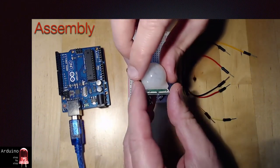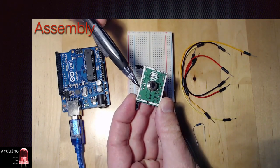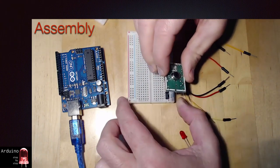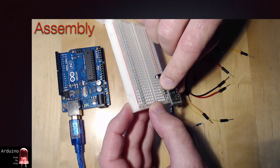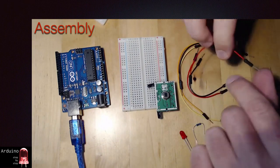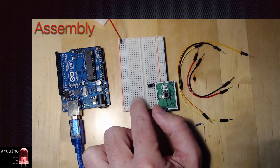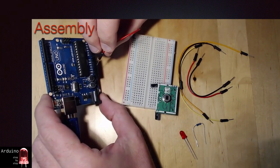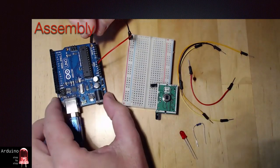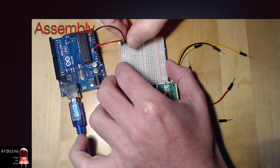Let's start with the sensor. Let's remove the cap off so we can have a look at the markings and be sure of what the purpose of each pin is. And just plug it anywhere on the breadboard. Then we'll take a red jumper wire and connect the positive voltage line on the breadboard with the 5 volt socket on the Arduino. And then we'll take the black jumper wire and connect the ground socket of the Arduino with the ground line on the breadboard.